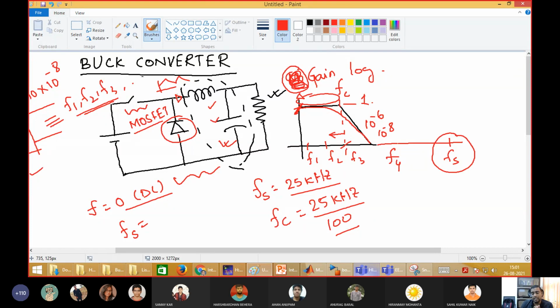Those are fine, but they have very high reverse recovery. There is a delay in those diodes and a very high spike in voltage and current during reverse recovery. Those diodes you cannot use in this kind of high frequency DC-DC converters.